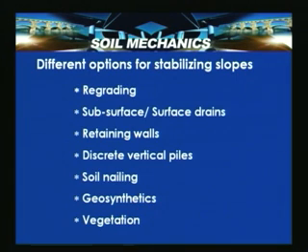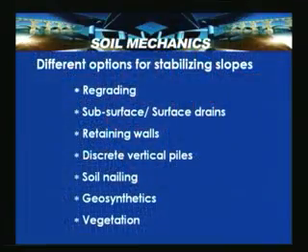Sometimes, for the sake of construction of steep slopes in urban areas, the slopes are initially strengthened by using certain reinforcement layers. That is called reinforced earth slopes, which are also possible in urban areas. But if there is an existing slope which has been investigated and found to require stabilization, then many methods are available. One of the options is regrading, that is removing the unstable portion and increasing the stability of the slope, that is, flattening of the slope.